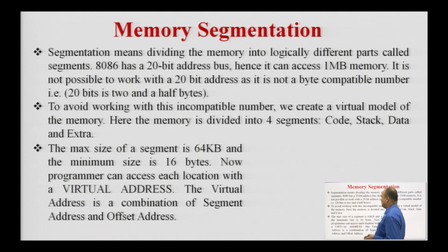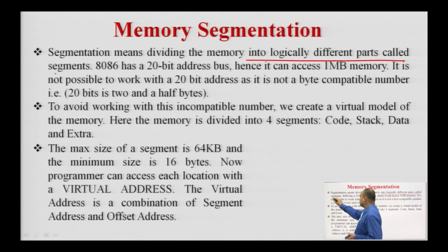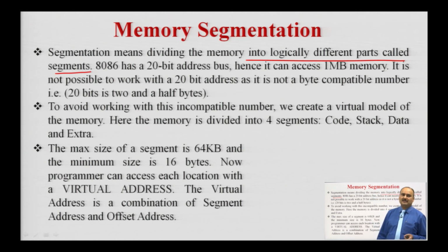Next is the memory segmentation. Segmentation means dividing the memory into logically different parts called segments. What is segmentation? We are dividing the memory logically into different parts. In the 8086 microprocessor, we know that it has a 20-bit address bus, hence it can access 1 megabyte of memory.